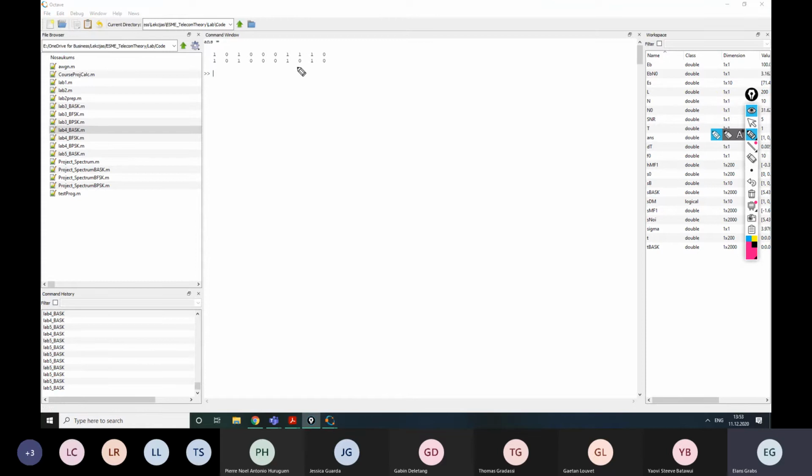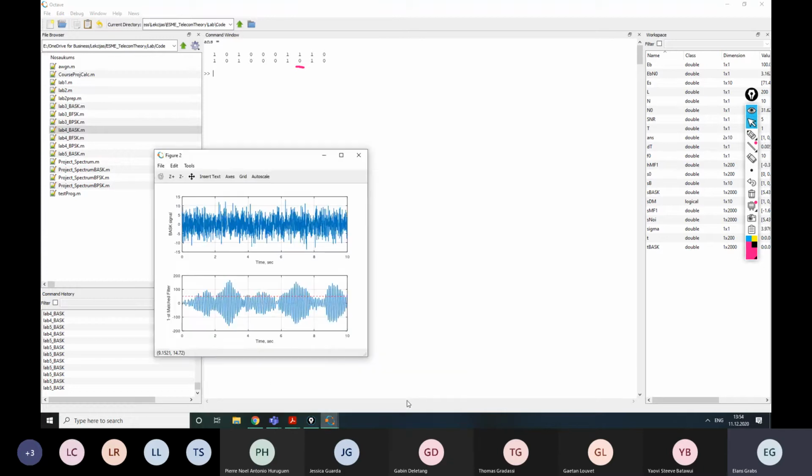Okay, I have encountered error here. As you can see, I have sent 1 and received 0. That happened at almost last signal, and let's see in the picture how it looks like there. So this is the last signal, and this is the 1 signal. Yes, you can see here that it's actually above 0. This one was below 0, and now here what we have received is actually below 0, below threshold, not 0, but threshold, right? So that's why it was interpreted as 0. However, in fact, there was 1.